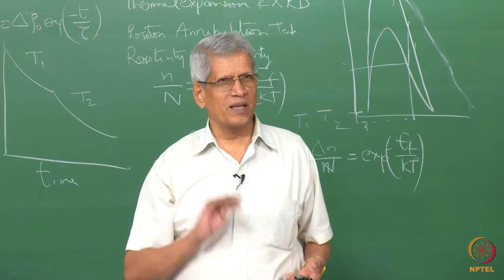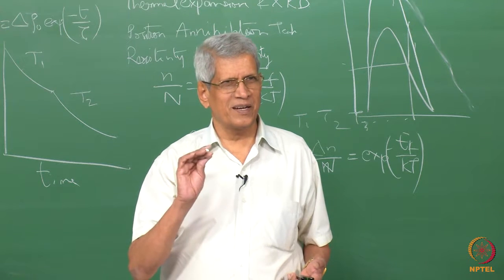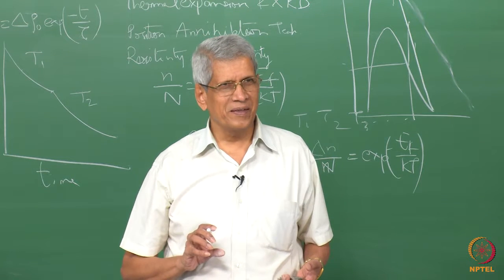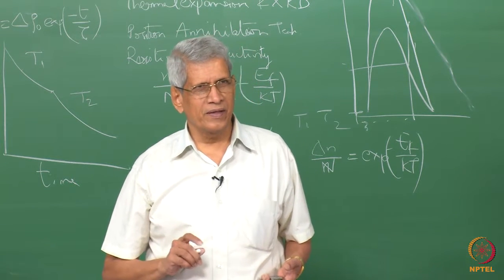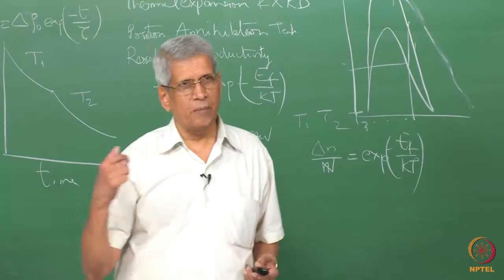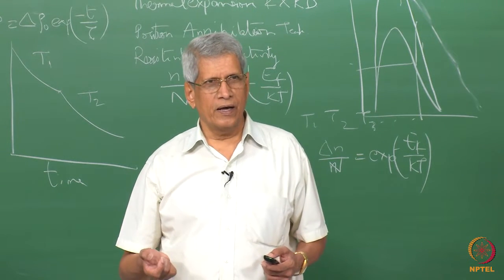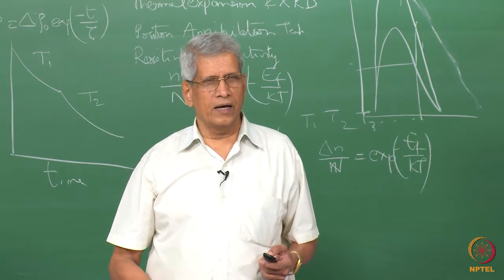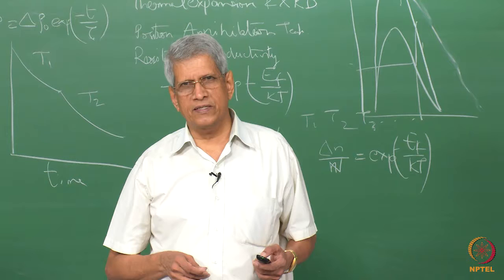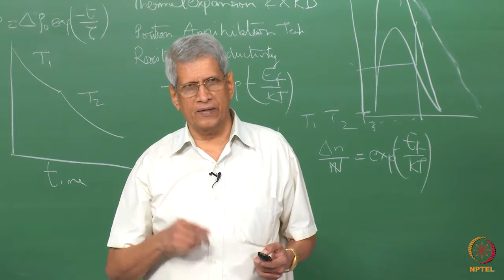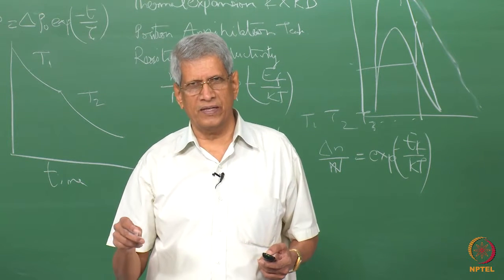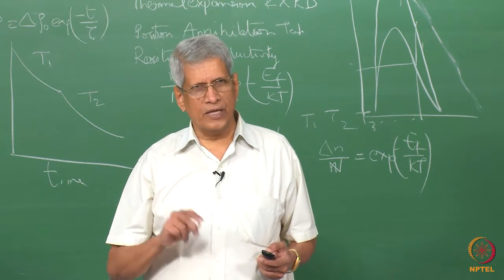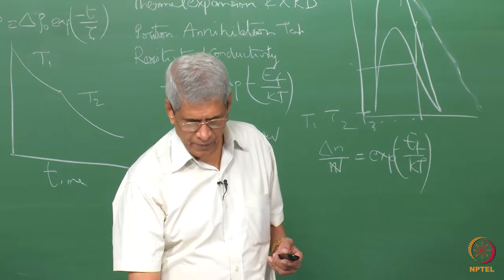So as a function of time, the agglomeration of vacancies to voids could be reduced considerably. This is especially relevant in structural materials for nuclear applications, especially stainless steels. Some titanium is added because titanium forms complexes with vacancies, so that it can reduce the vacancy mobility.